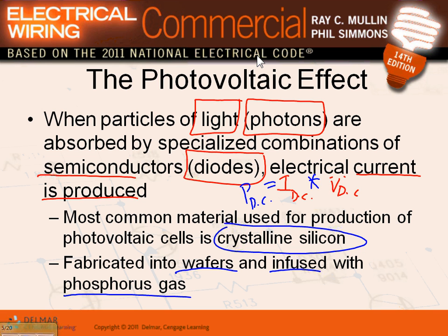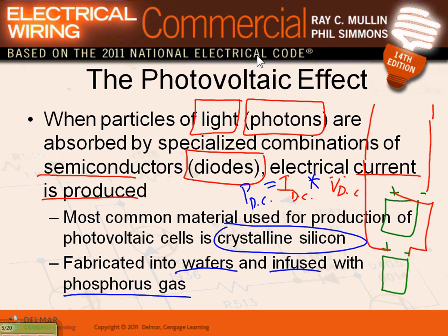So I'm just going to draw a little bit of two solar panels here, and I'm going to say positive, positive, negative, negative, and I'm going to tie these two, my friends. I'll bring this one into here and tie it into here. So I put them in series, right? Suppose that was 5 volt and that was 5 volt. What do you think, guys, the output here would be?